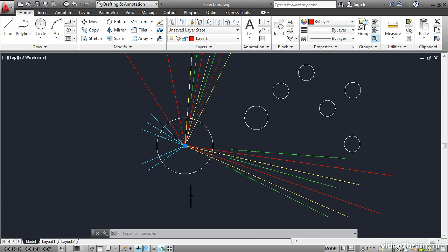The last selection method I'll leave you with works without issuing a command, so you don't even need to be at a Select Objects prompt for this method to work. Select a couple of objects, and this turns on their grips. Hold down the Shift key and move the mouse over one of the grips and click. The grip turns red.